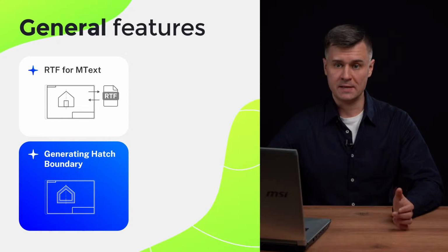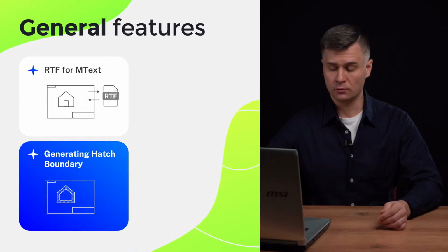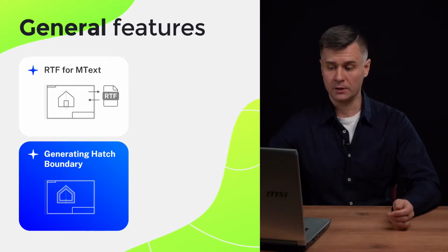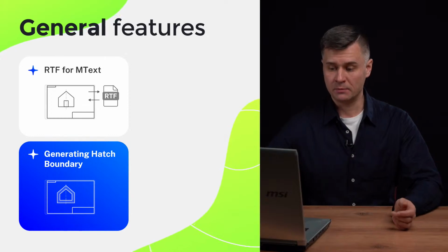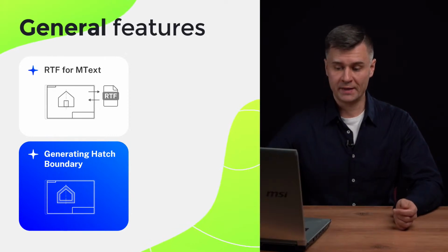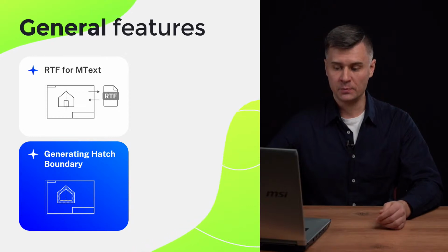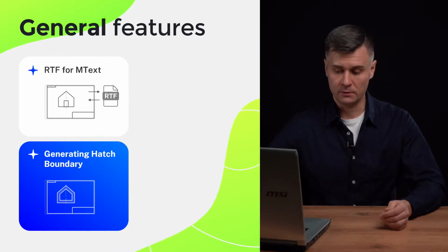Just a reminder, the boundary allows to create an entity with a closed loop for multiple entities in a specified area of a drawing. In addition to pure boundary, hatch creation has the possibility of closing contours with gaps, and gap size may be managed by means of the HPGAPTOL system variable.